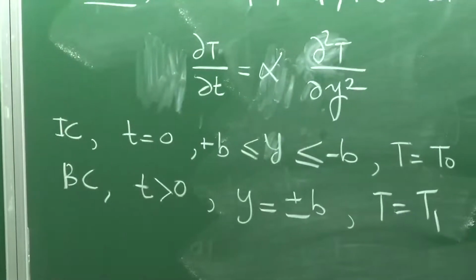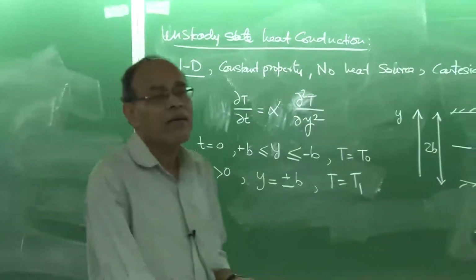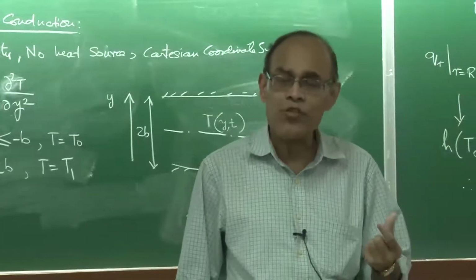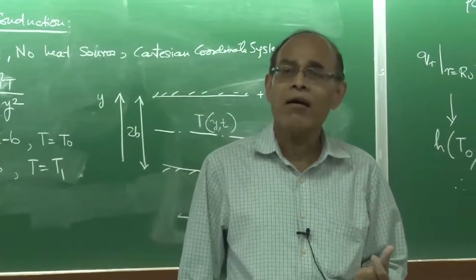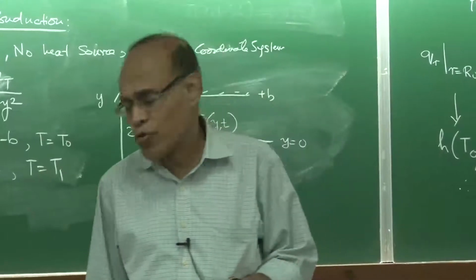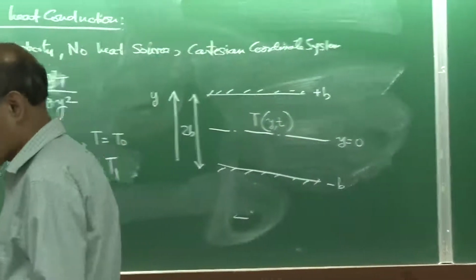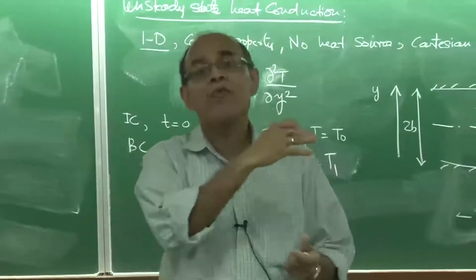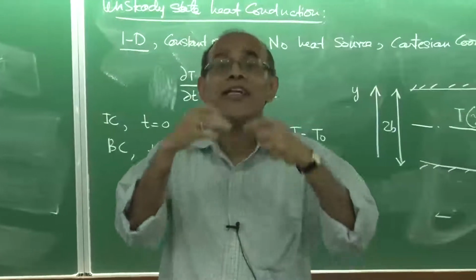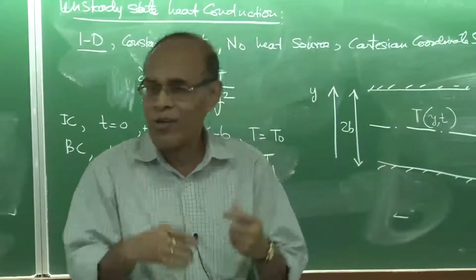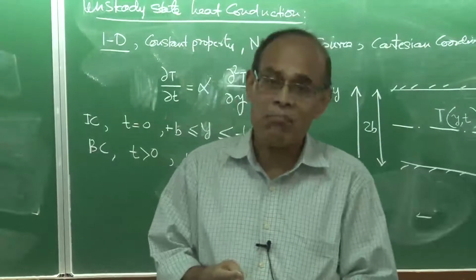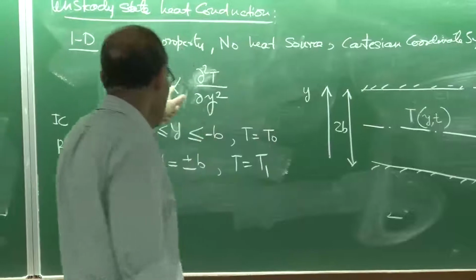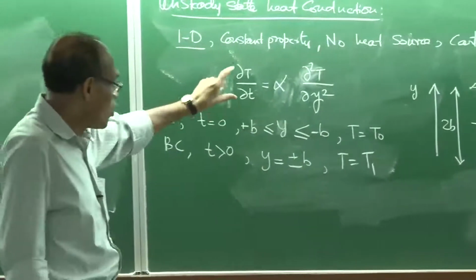Now, in that context, you remember that I have not shown you explicitly, but I said that when I wrote the Navier-Stokes equation, which contained inertial force, viscous force, gravitational force, as well as pressure forces, since each term is a force, if you divide it by one force all through, you can get the equation in non-dimensional form, and in that context I said that we get Euler's number, Reynolds number and Froude number. In this case also we can non-dimensionalize this equation.